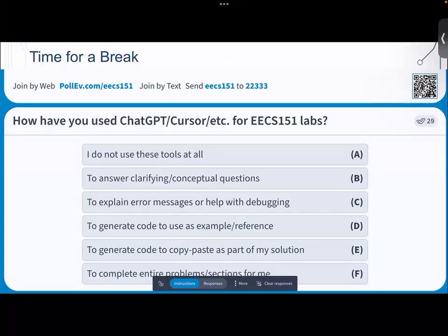Not universally. We talked about how there's a trade-off. Generally larger gates will have stronger drive. They'll be able to drive the next stage faster. You'll see some scenarios where making gates smaller will make them a little slower, but will save a lot of energy.